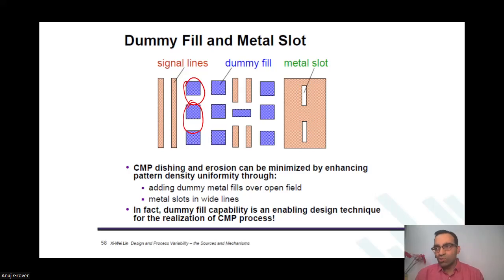Now, at the stage of going on silicon, the system says, oh, there is sparsity of metal 3 there. Let me add dummies of metal 3. So above your IO now, there are dummies of metal 3. What happens? The capacitances of underlying metal 2 would change. The capacitances of other metal 3 lines in that region would also change. So finally, what will be fabricated on silicon will have a very different RC than what you characterized, what you validated, what you designed your circuit with. Can you afford this variation?